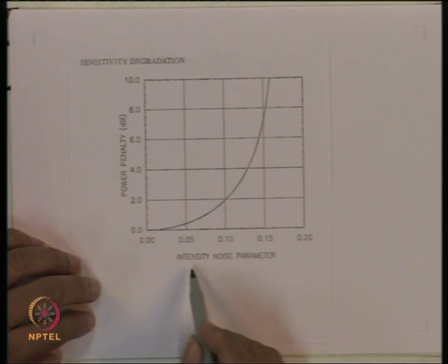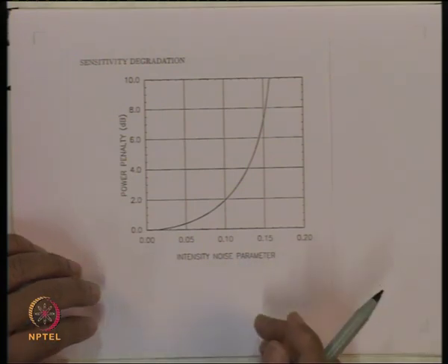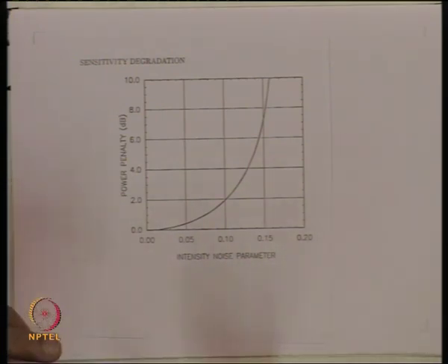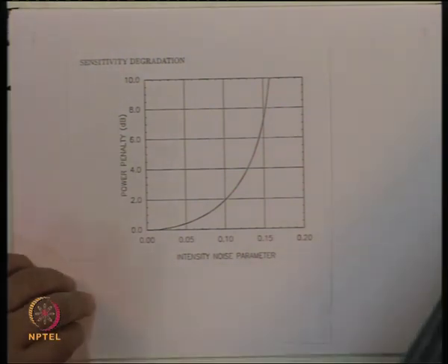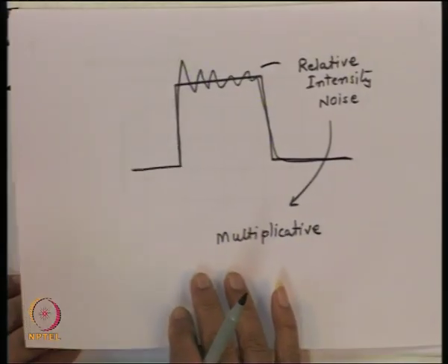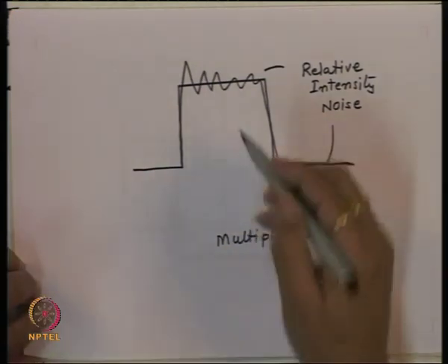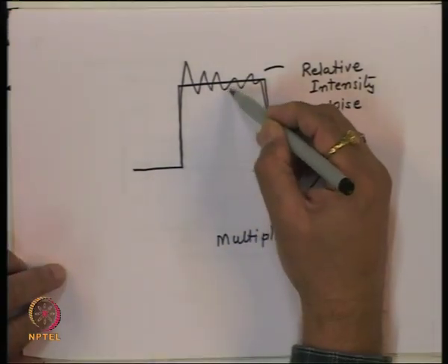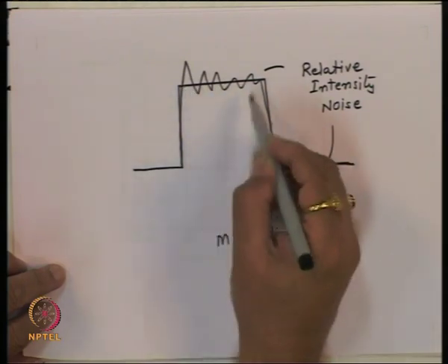Now note here, the noise which you are indicating here is essentially indicating a value of sigma of the relative intensity noise. The peak to peak deviation of the noise is about 5 to 6 times sigma. That means one-sided deviation, you have approximately 2.5 times sigma deviation of the signal corresponding to mean level on one side.